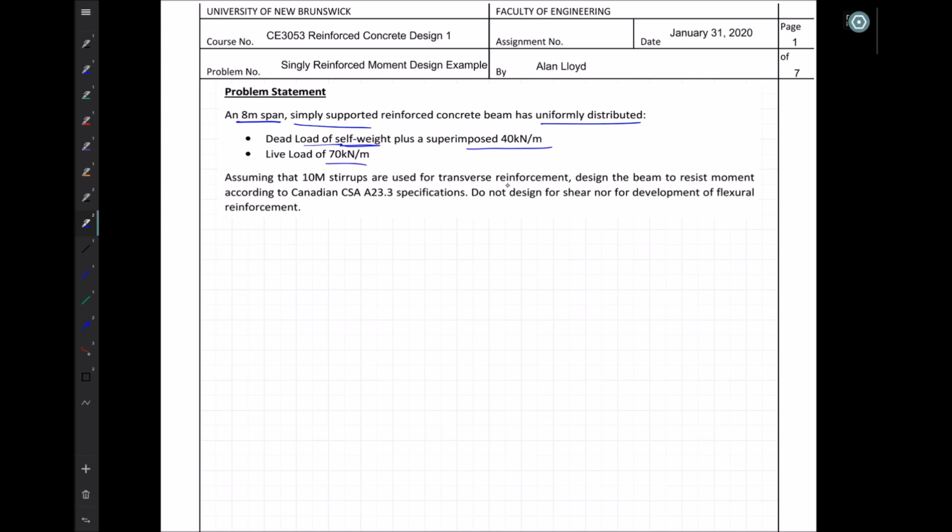We note that if we don't know the self-weight of the beam already, it presents us with a slight challenge in that we have to assume a beam weight to determine the self-weight and then design around that assumption. So we'll have to do a few checks and balances to make sure that we assume a correct value and that we incorporate the refinement of that value as we refine our design.